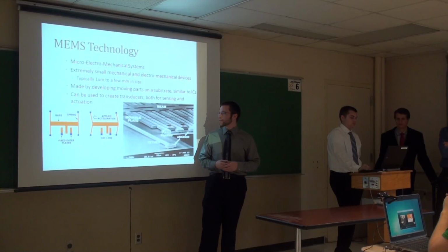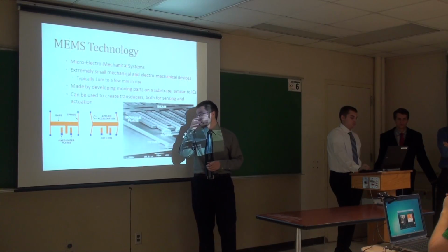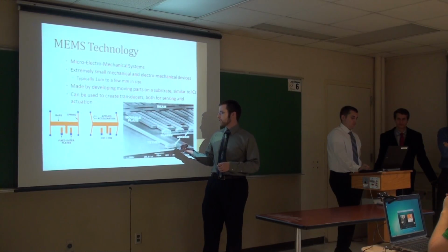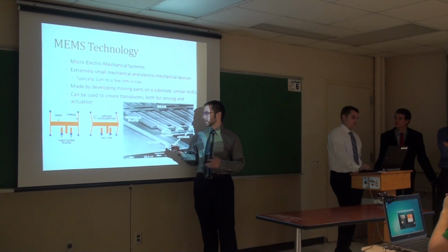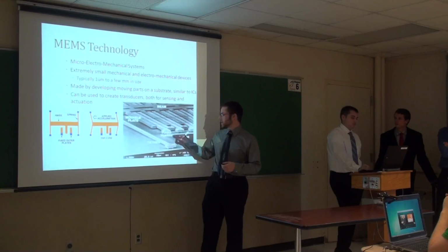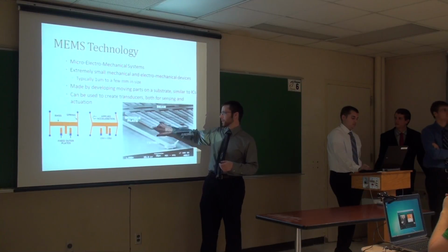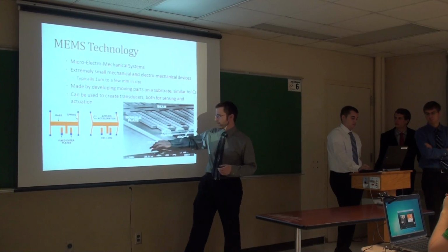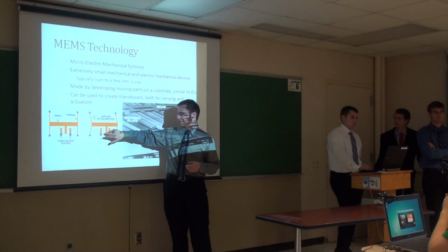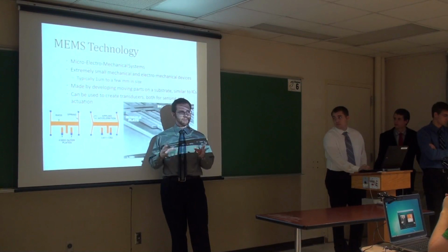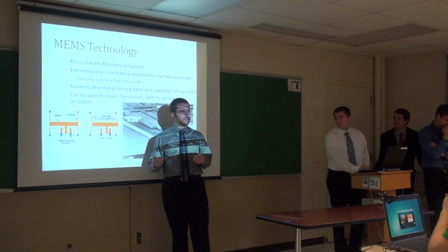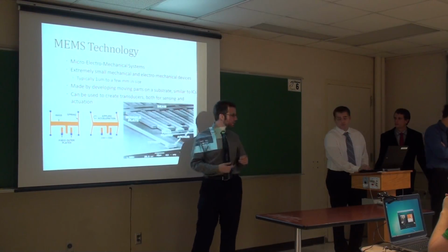Like DJ was saying, there's capacitive accelerometers, and here's actually a close-up of a capacitive accelerometer in MEMS terms. You have these fixed plates here, and then the movable plates. That movable plate will move in between the 2 fixed plates and create a difference in capacitance, which correlates to the difference in voltage.